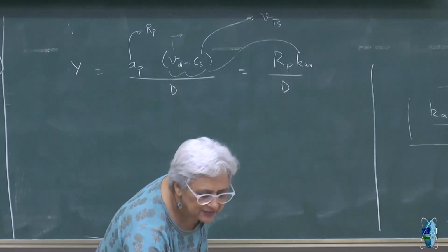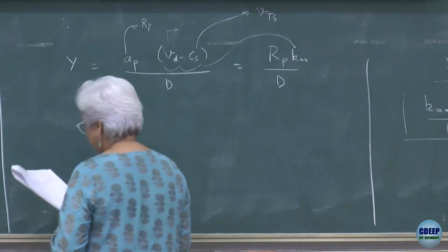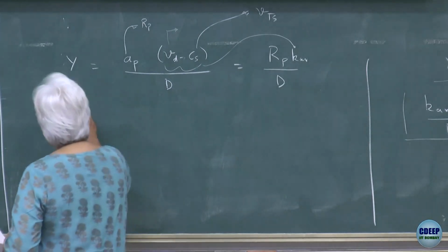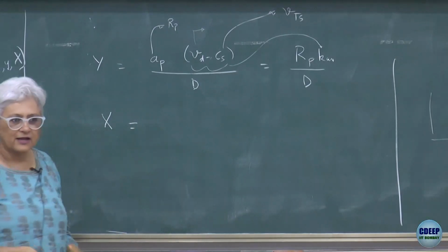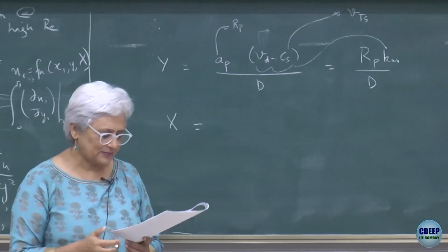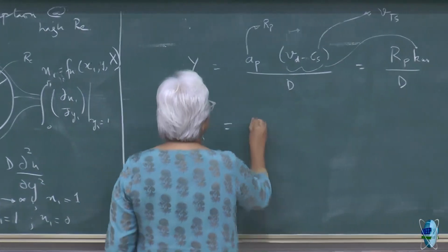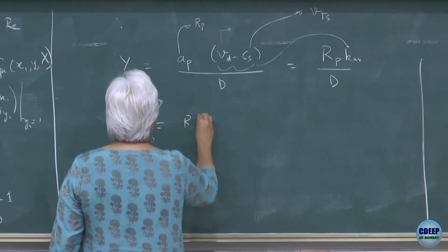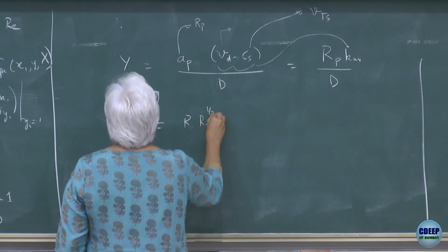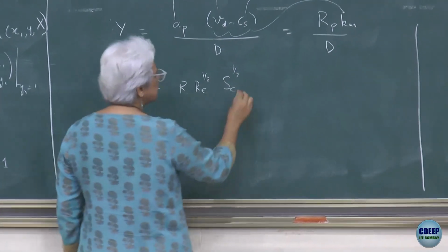And what is there on the x-axis? I told you sometimes it's called a pi, sometimes it's called an x, etc. It's nothing but our non-dimensional parameter over there. But what is it in terms of? R, Reynolds to the half, Schmidt to the 1/3. And what is the Schmidt number?